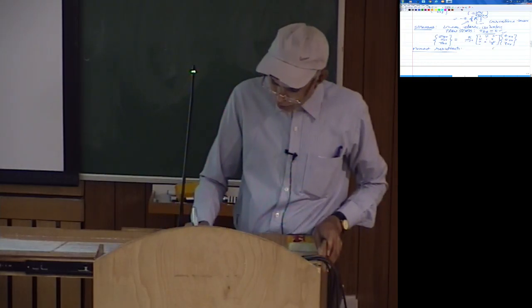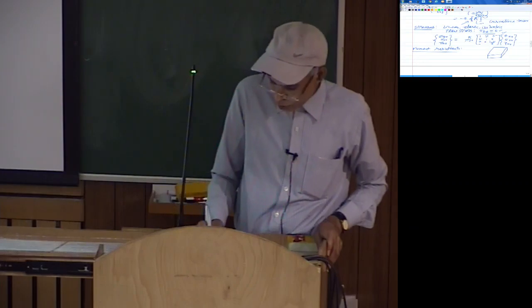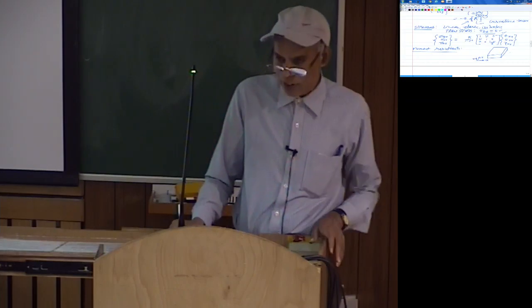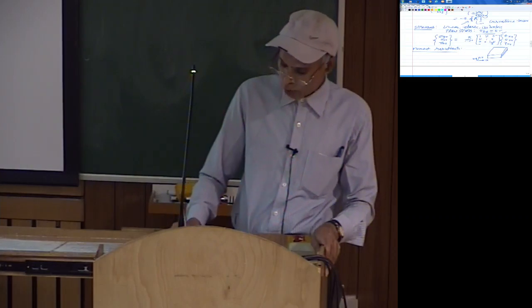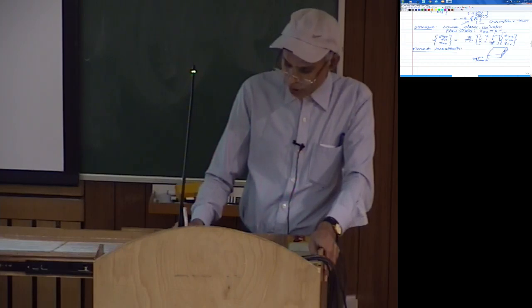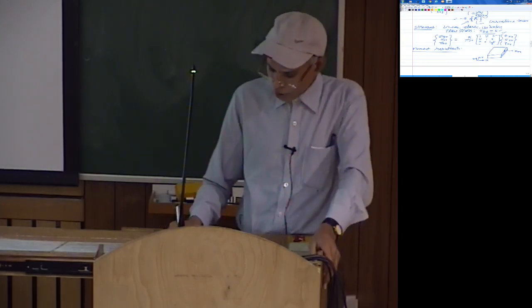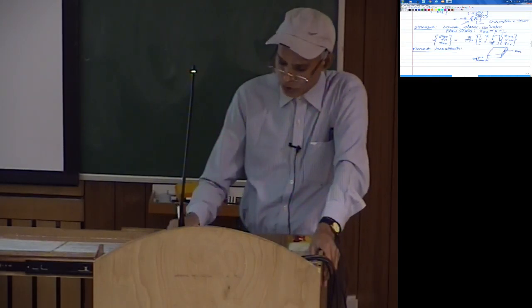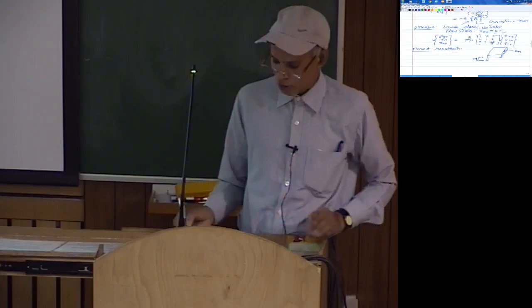What I basically mean here is that if you have some segment of the plate, and you look at the same coordinate directions, this is x, this is y and this is z. For this face, somewhere here you are going to have your middle surface, and the outward normal is along the x direction. If I take a small differential area on this face, there will be a stress sigma xx, which of course varies through z, because the strains are linear functions of z, and therefore the stresses will also be linear functions of z, so we will have a linear variation.